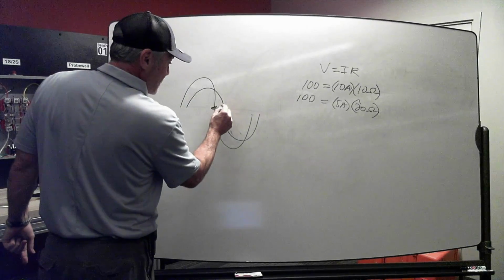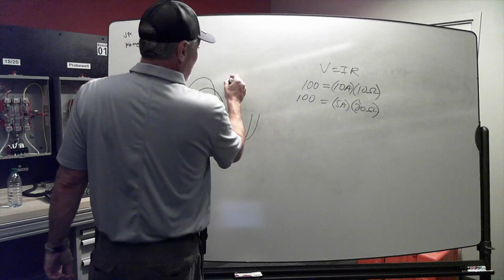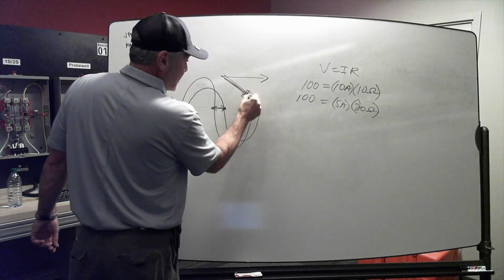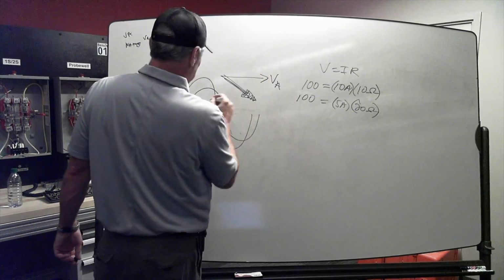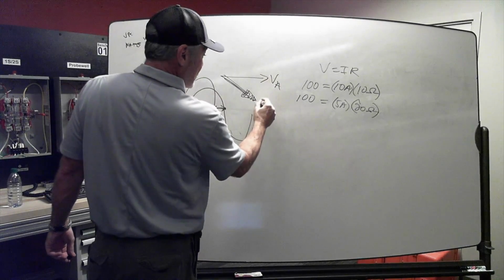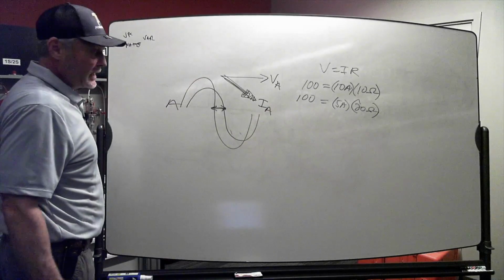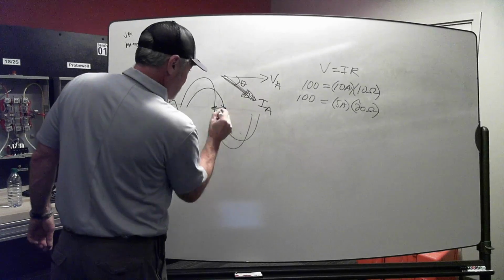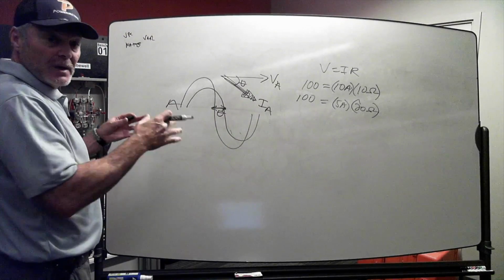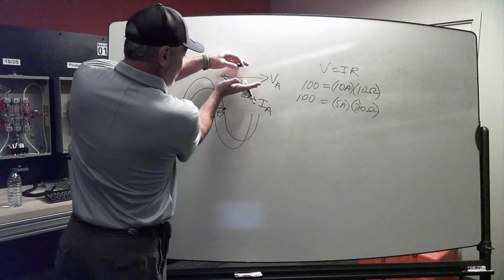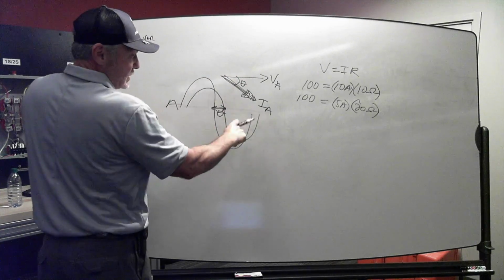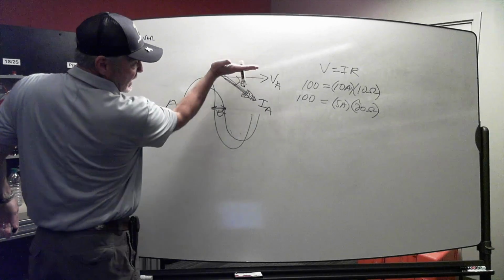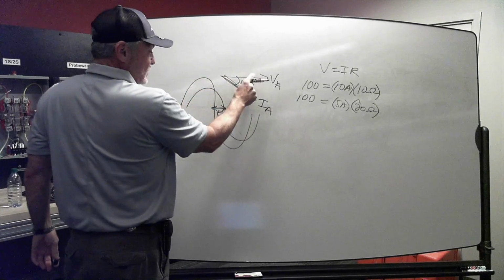This right here is equal to, remember, we've looked at it 100 times, the angle between my voltage, let's say this is A phase, this is my voltage on A and my current on A. This equates to this, okay? And so they've taken it and made it a lot simpler for us, so that we don't have to use an O-scope and look at this. We can just look at the angle between my voltage and my current, and that angle is theta, the same angle.